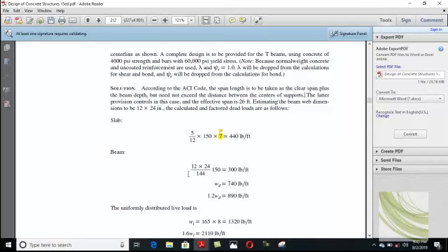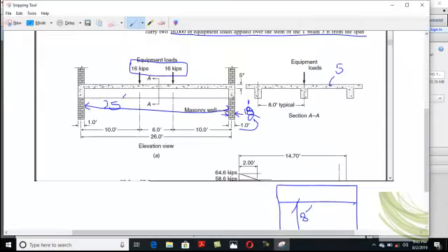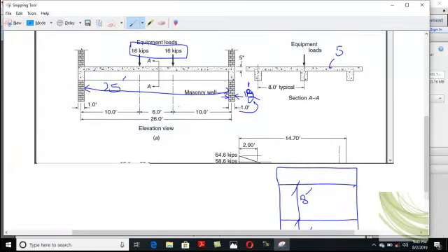So how much is that length? That is known as effective length, and that effective length starts from the ACI code, which says that your span length is equal to your clear span, that is 25 feet, plus 1 depth, that is the effective depth of the beam. Clear?